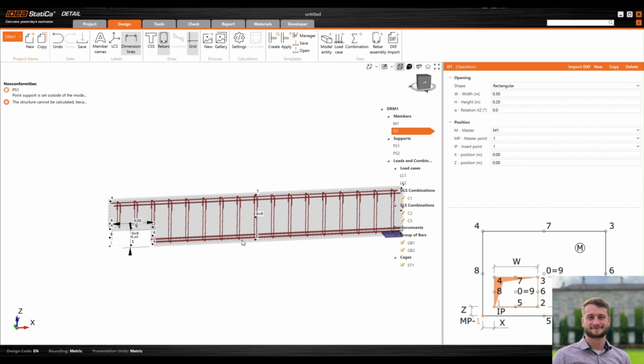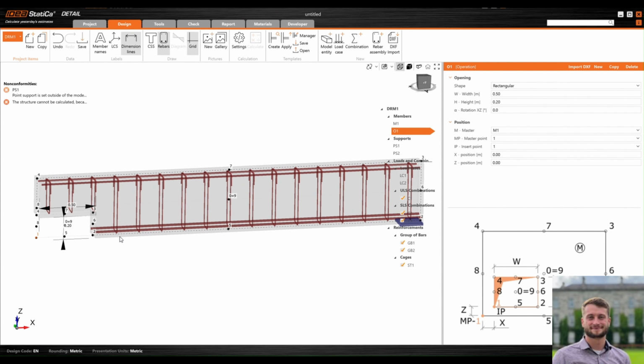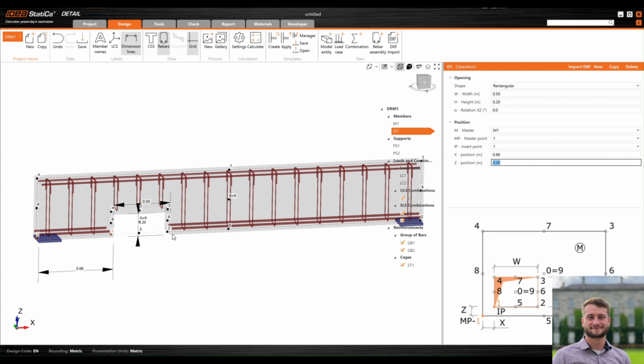So now recalling the dimensions we took there from the ISC model, we can set this fella out. So the X direction, which is along the length of it, he was 460 millimeters, but we add on the extra 200 again because of the bearing support on the left-hand side there. So 660 millimeters, 0.660. So that's going to move him along to where the opening is in the X direction, and in the Y direction, he is 155 millimeters.